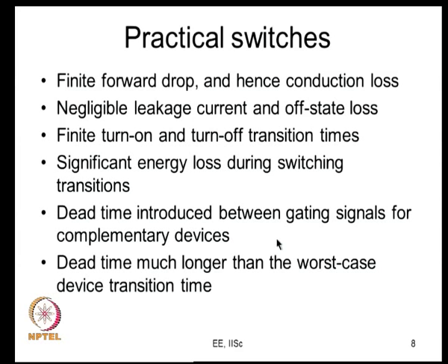What you need to do is, if there is a device which is on, you first turn off that device and then you turn on the next device. So, you wait for a short interval between the two, and that short interval is what you call dead time. The dead time is introduced between the gating signals for the complementary devices, which are actually the top and bottom devices in an inverter leg.